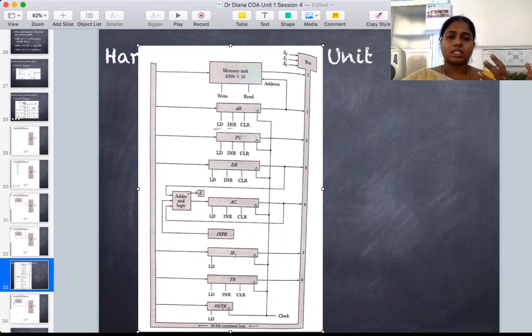This is a basic model in which different parts of the computer interact with each other. So when I say the accumulator has to read, one control signal to the accumulator is made high and the corresponding accumulator is activated in the bus circuit. Whatever is in the bus will be pushed inside the accumulator. That's how it works.